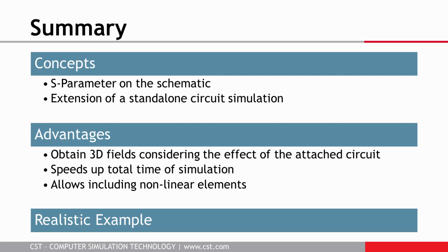The advantage of such a coupled simulation is of course that you can visualize 3D fields that have been calculated inside the 3D model, considering the circuit that has been attached to it. This is very powerful in debugging your hardware because you can really see fields, and you can see currents flowing on your structure the way they actually do when the circuit has been attached. In many cases it can speed up the total simulation time, and it also allows you to include non-linear switching elements and visualize their effect, again in terms of currents and fields of your 3D structure.